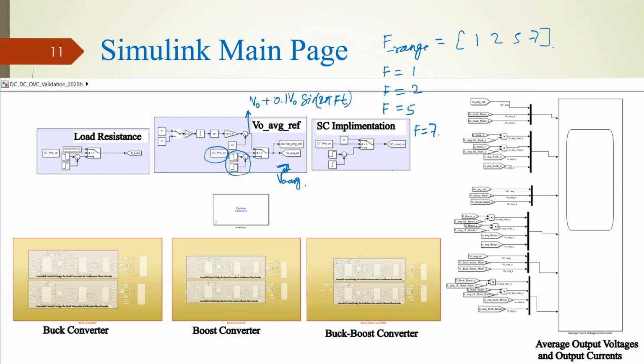And this is for implementing the fault analysis, I mean the fault on the load side. So we would like to do a short circuit on the output voltage and see if our converter and our controller are operating safely or not. And we have this big scope.